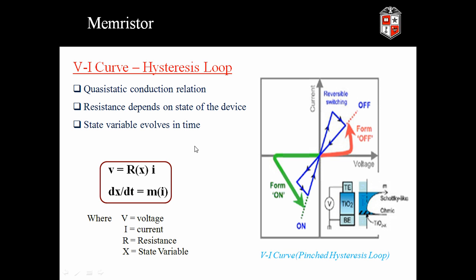We are saying that the memristor is a fundamental element. How can we say that the memristor is a fundamental element along with the resistor, capacitor, and inductor? This region here in the third quadrant gives the memristor its fundamental property. By using any combination of resistors, inductors, capacitors, or any other present circuit that we have, it is not possible to achieve this property in the third quadrant. As it is the only element showing this property, the memristor can be considered a fundamental element. Chua also proposed a statement: any element that shows a pinched hysteresis loop in its VI curve can be considered a memristor.